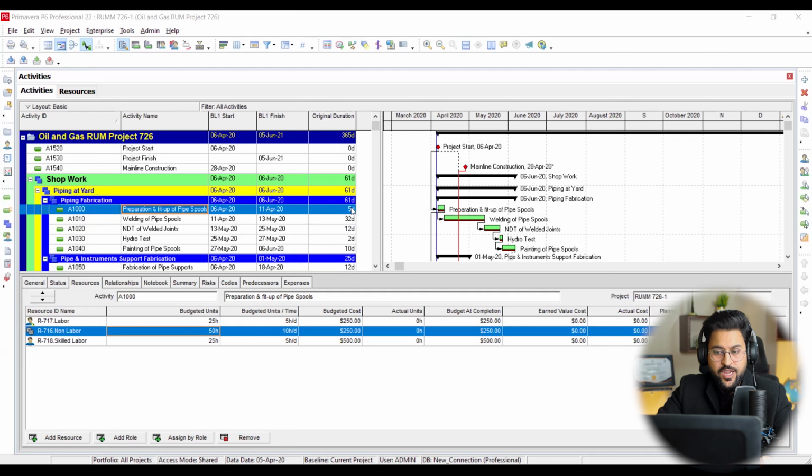My plan is time driven, right? So I have to arrange my resources, whatever the quantum of work is there. I know that I have to calculate the total man hours on the basis of my productivity. These productivity sheets are going to help me out. I will share another sheet with you, and this is going to help you understand how these productivity sheets along with the crew composition are going to help me out.